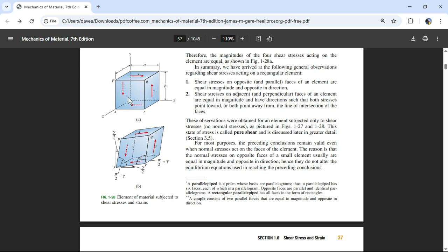And what we do is we just make a chunk of material that's another square. It doesn't matter what the size of these squares are, because this is a pressure. It doesn't really matter what the size of this element is. So I can make a smaller element at a 45 and make a smaller cube in here at a 45-degree angle.